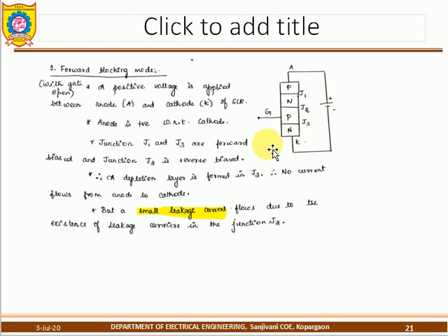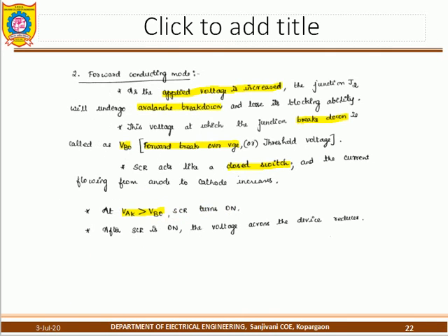Here you apply the anode current, and this side you increase it. What happens due to that? The gate to cathode side increases, and it is the breakdown. The blocking reduces, so the current flows from anode to cathode. In that case, VAK is greater than the breakover voltage, so the switch is closed. Now it has moved to the conduction mode.